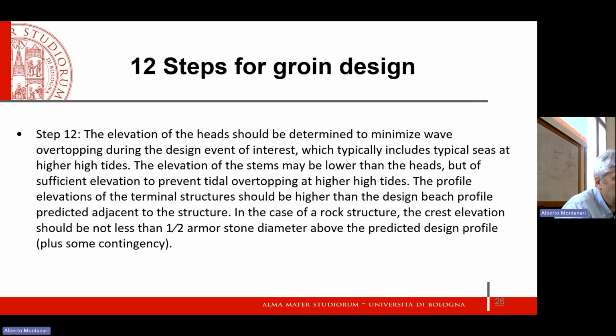And if you have a rock structure, usually it is recommended that the crest elevation over the post-project elevation of the beach should be not less than 1/2 of the armor stone diameter.